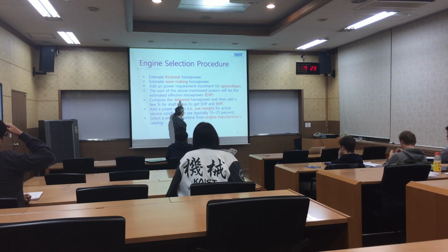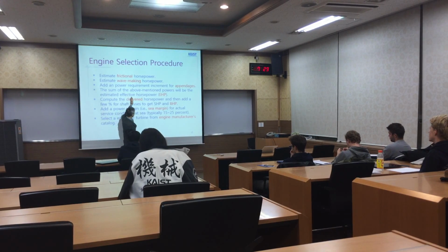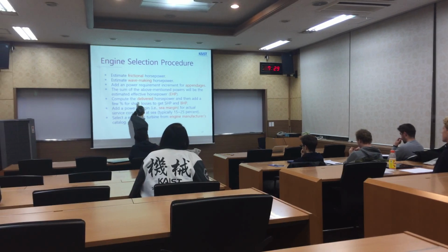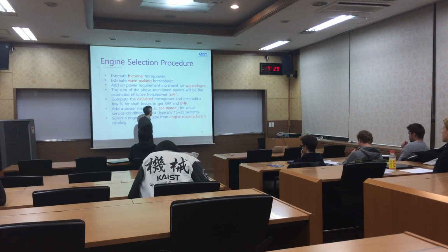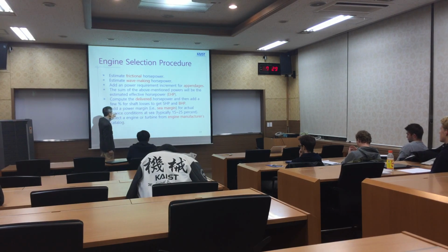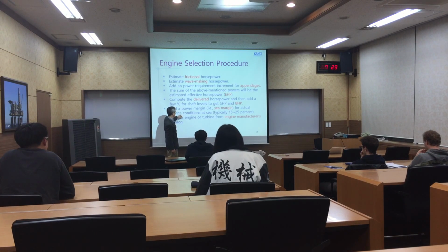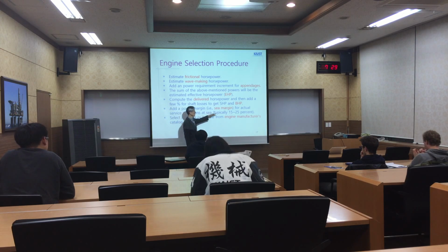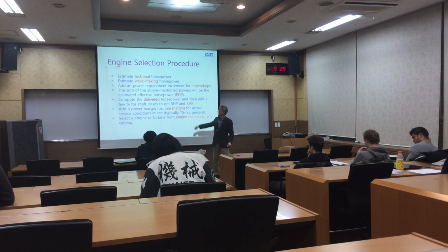Right? So effective horsepower and propeller, and before that is delivered horsepower, and before that is the stern tube. The stern tube, let's say, is shaft horsepower, and the gear, if there is a gearbox, gives brake horsepower, right? And then finally we arrive at the sea margin, because there are waves and wind, and we also have some uncertainties inside our estimations.